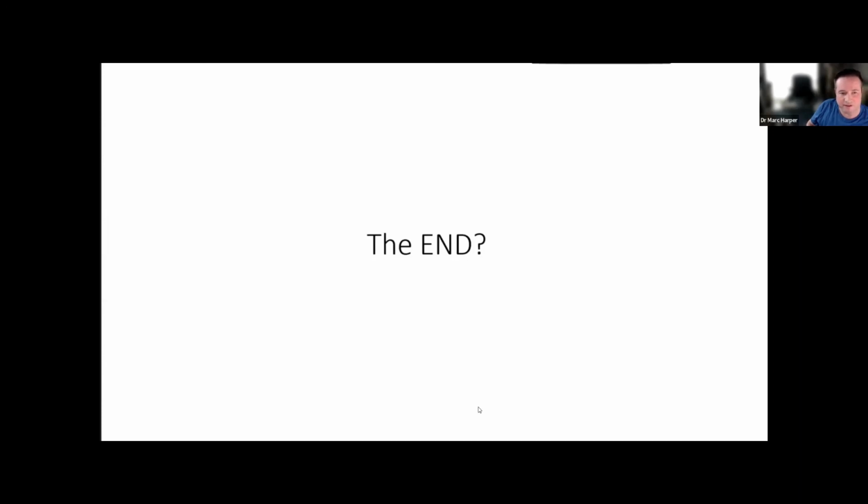So yeah, they are important, but we really focus on getting the bandwidth across the antenna and maintaining the efficiency of that antenna across that bandwidth. And also the amount of SAR. Those are the three top metrics we look at. I mean, this is important, but it's not the one we optimize for. We're optimizing for different things.